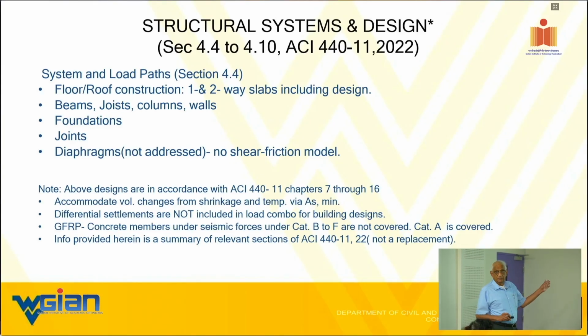I already told you many times, in a casual manner and in a serious manner, FRP concrete members under categories B to F are not covered. Even category A is covered only as a pseudo-static response, not as a true dynamic response. As a note of caution, perhaps a disclaimer, all the following slides are a summary of what is in the code. I'm not trying to replace the code.